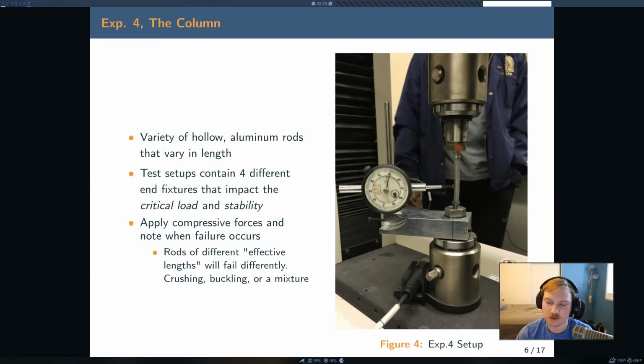The hard part, and you can see this dial gauge here, is measuring the deflection, how much it deflects outwards. That's a huge pain, mostly for these short columns. You see here, this is deflecting on this side. So this dial gauge should really be over here from the very beginning, but it's hard to know which plane the short columns are going to deflect outwards. So it's really hard to measure that deflection because you've got to be on the right plane.